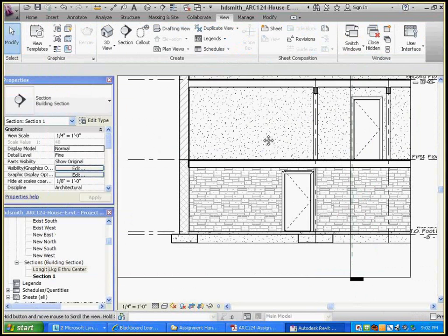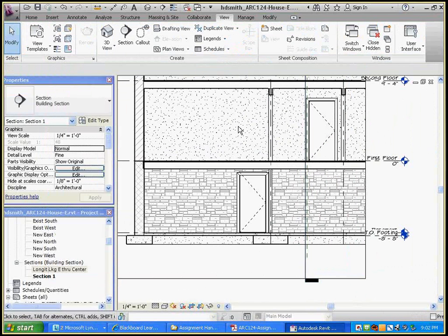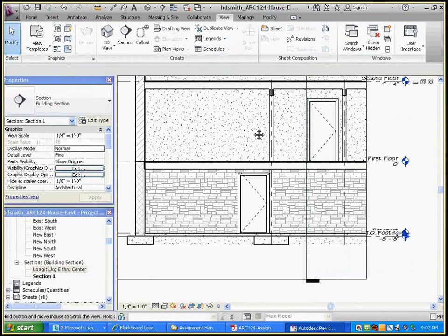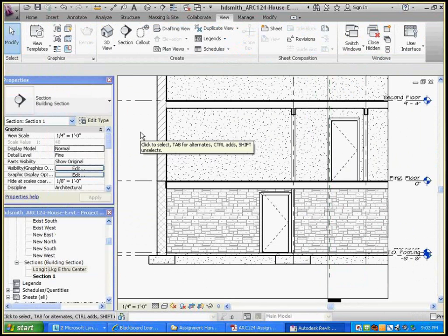So now, since it's supporting the first floor, and for those of you who aren't architects or structural engineers, there's this disagreement between architects and structural engineers as to what constitutes a first floor plan. An architect wants to show the walls going up from the first floor on the first floor plan. Structural engineer for a first floor framing plan actually wants to show the columns that support below the first floor, and they don't really care about the walls that are going up because they only care about the structure that supports it and then any structure that bears on it.